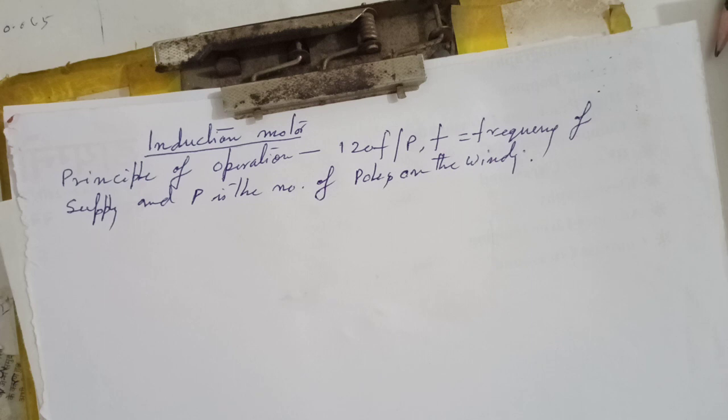When the three-phase supply is given to the stator winding, a revolving magnetic field is created, so the speed of the rotor is always less than the synchronous speed.